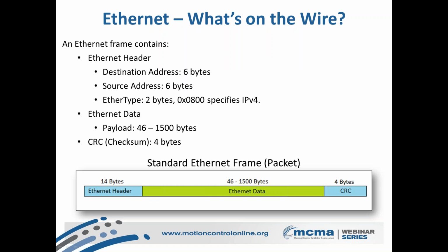So really quickly, we can go through the difference between the bits and bytes of Ethernet versus EtherCAT. In this image, we have a standard Ethernet frame, known as a packet. The first 6 bytes is an address, called a MAC address, and then a source address. So where is it coming from? Where is it going? And the EtherType specifies which protocol,